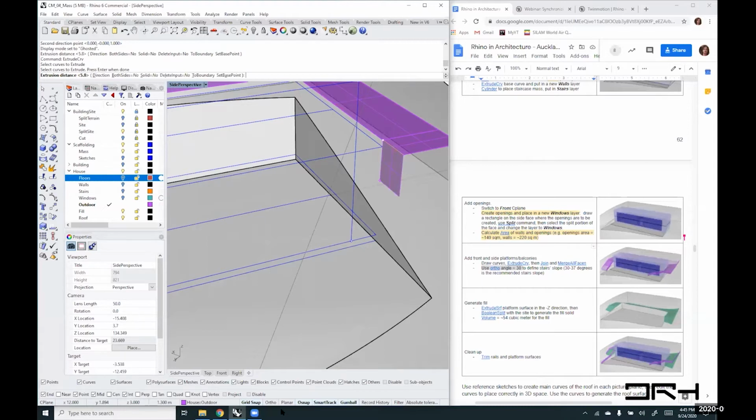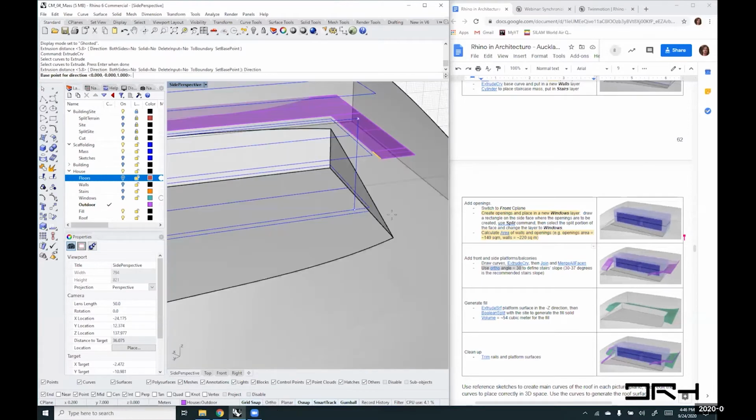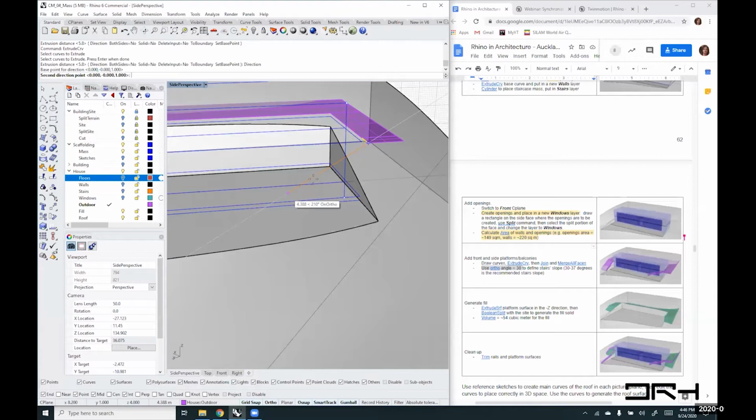And because my ortho is set up to be every 30 degrees, you can see the guides. If I move my cursor closer to angle 30 or 60, it actually shows. And you can immediately say, okay, this is the 30-degree angle that I'm interested in, and then you are locked to that direction from that point on. Does that make sense? Yeah. Sweet. Yep.